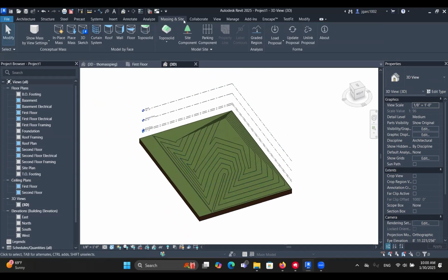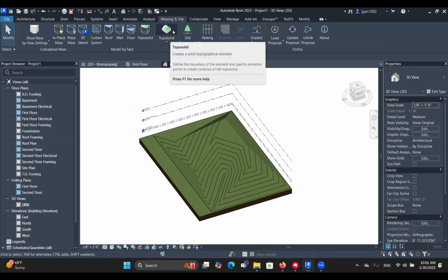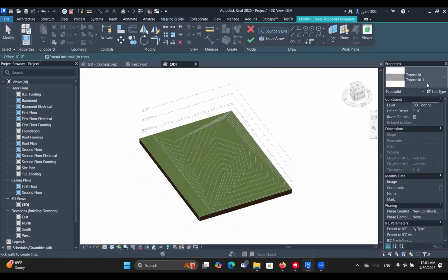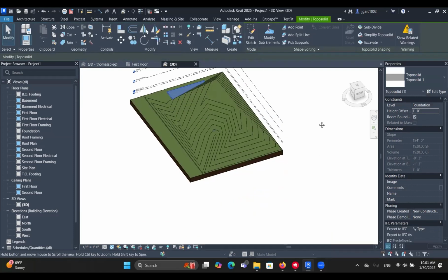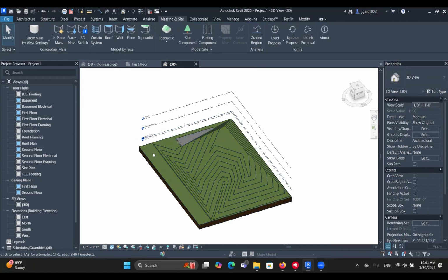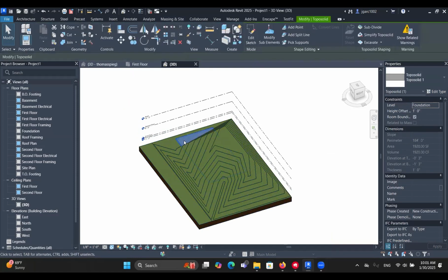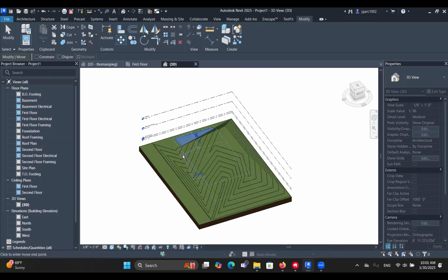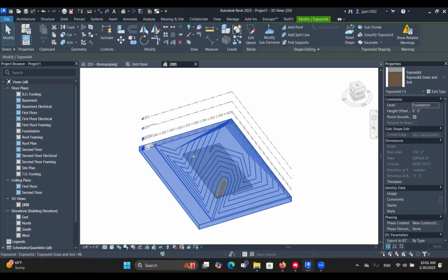And if you were to do then say the foundation of your building, or the flat foundation of your building, you want to go for the regular topo solid, you're going to want to do the foundation. Maybe let's raise it a foot. Let's come here. Let's do that foundation. Then it's going to tell you that it's overlapping. Now, if you have this problem, then it's probably because you do have to excavate like you would in a regular site. So hold on, let me move it there. You just hover over this one, and you're going to have the option to excavate here.